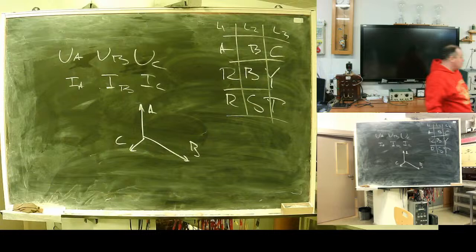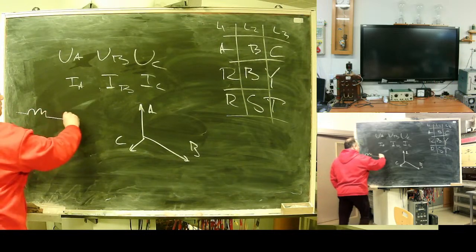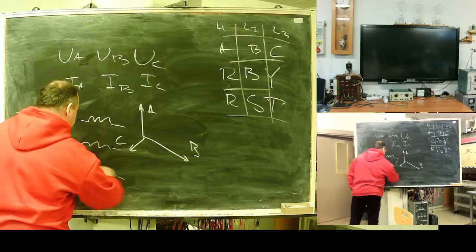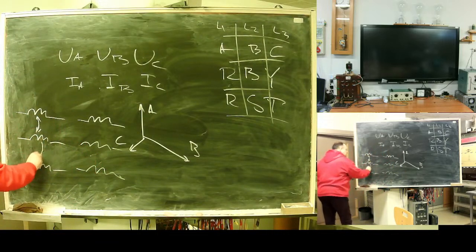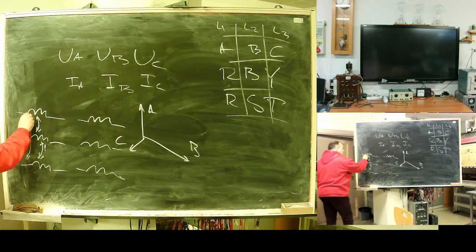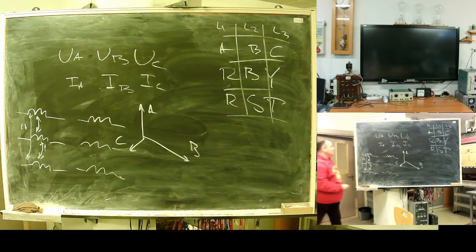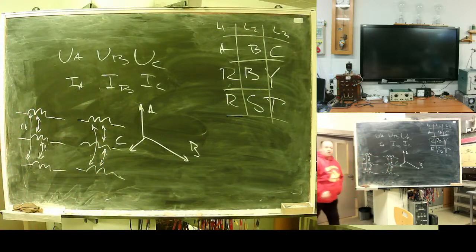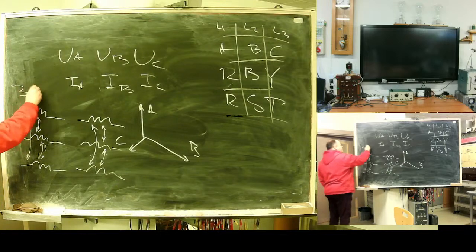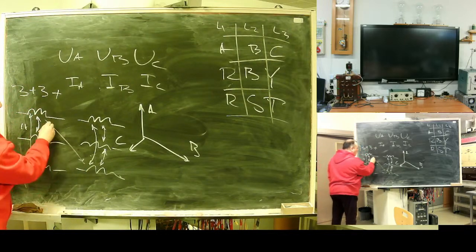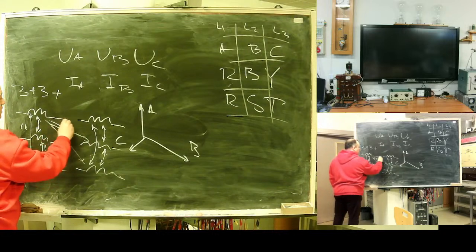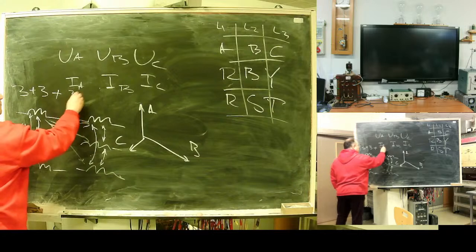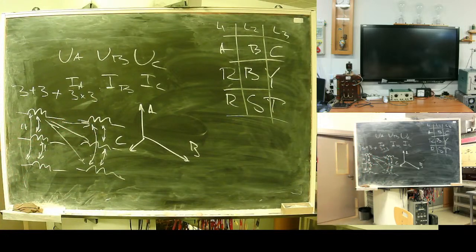Transformer. In case of transformer, you need to take into account three mutual inductances at primary side, three mutual inductances on a secondary side, 3 plus 3 plus 3 by 3 matrix of mutual inductance side by side.